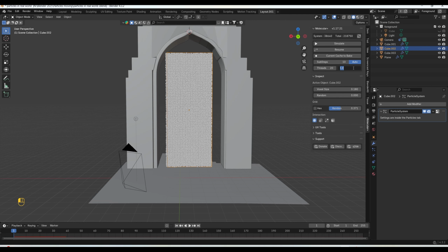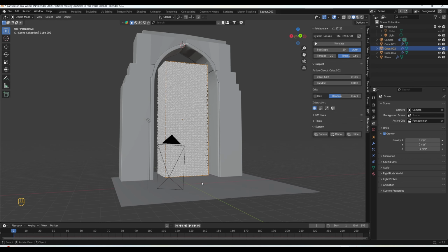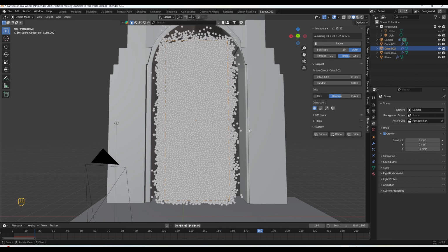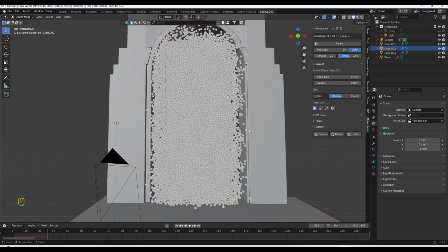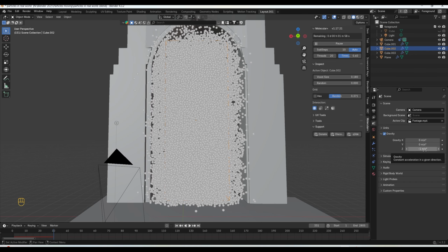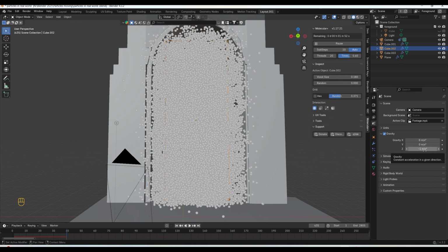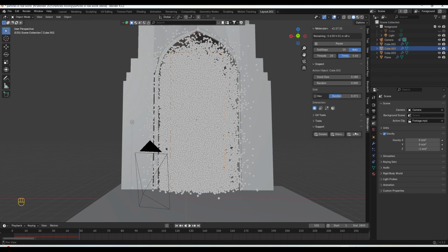So here in the time I will make it 0.5 or 0.6 for now, and it is also falling. So I'll go to the scene properties, and this is gravity, so I'll make it gravity -1. Basically I'm reducing the gravity so it will fall slowly. So let me simulate. Our goal is to add a turbulence effect to move and twist particles, and that's why we reduce the gravity. We want our particles to stay still and the turbulence to play its job and make particles move and twist everywhere. This is our main goal. That's why we did all the settings.